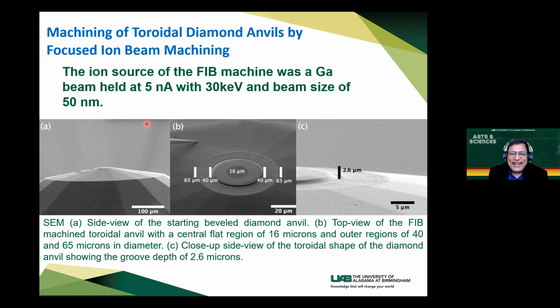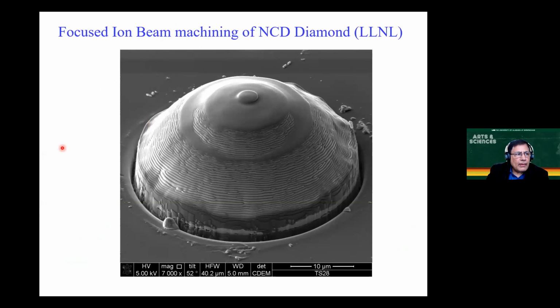For example, the experiment I showed in the microcrystalline diamond growth, what we really found was that the failure was not in the material we have grown, but underneath, within the single crystal diamond. And that is not surprising because shear strength is maximum, depending on the culet of the diamond, at some point deep inside the diamond.